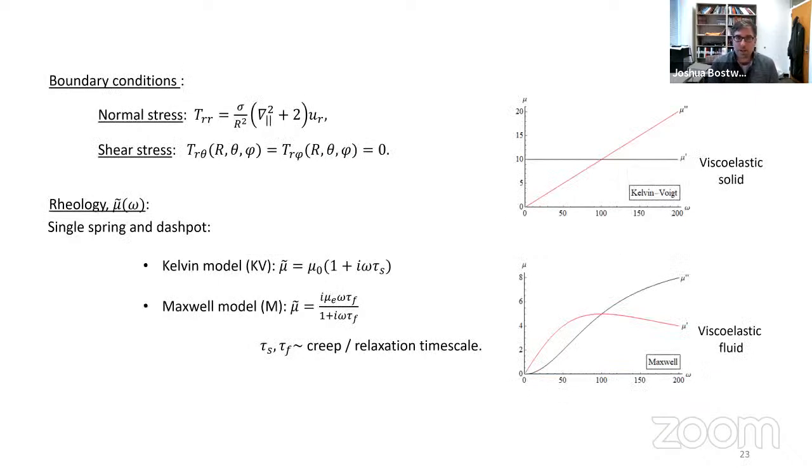And for a soft gel drop, or for a soft drop, the balance of normal stresses at the surface must be balanced by the surface tension times the curvature, the Young-Laplace equation. And we also assume that that surface is shear-free.